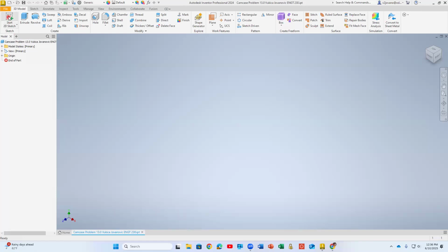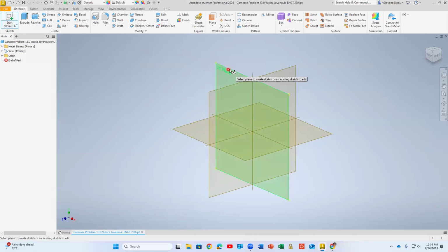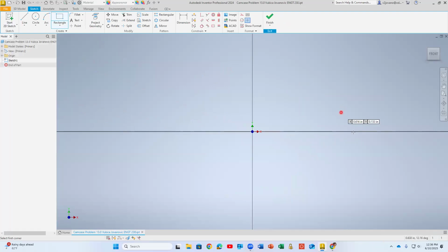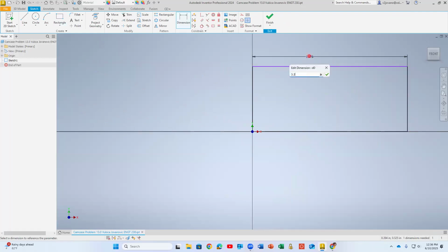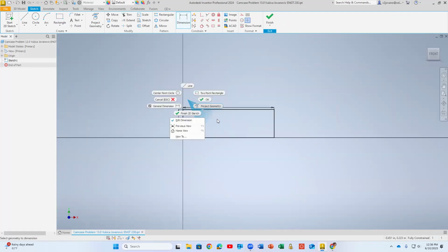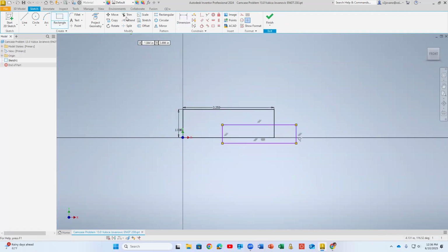So we will do this 2D sketch. I will again select the XY plane, and I like to use the coordinate system indicator. So here again, we have two rectangular shapes. So one is 3.250, and the other one is 1. Middle mouse click twice. And I just like to cut. I mean, you can draw lines as well. To me, it's just easy to use the trim command.